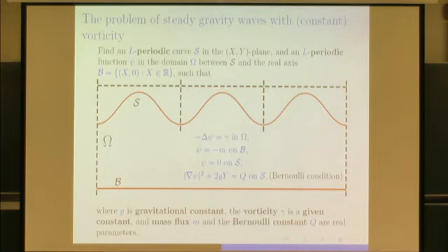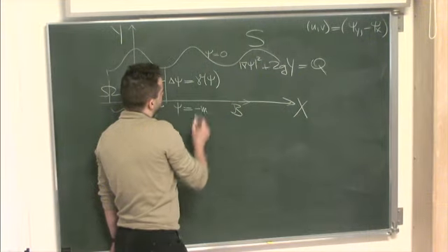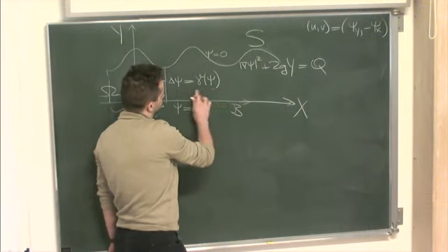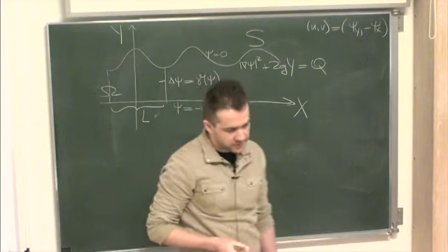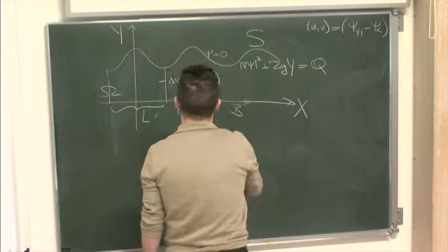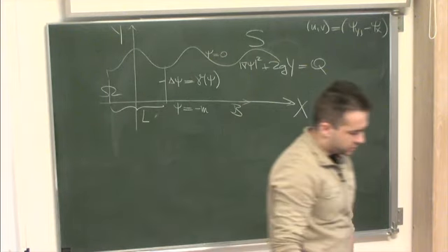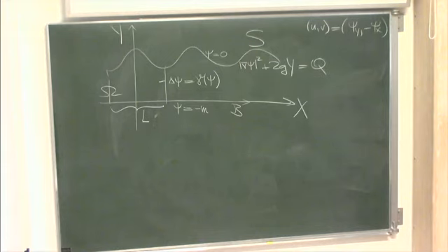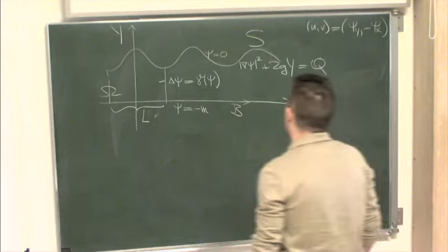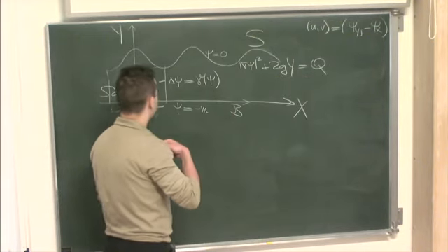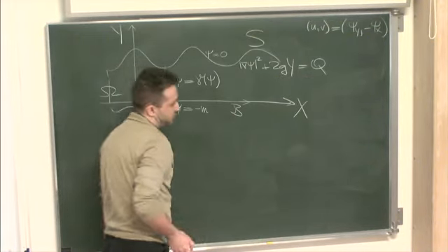So this is a particular case of the problem of waves with general vorticity, in which on the right hand side of this equation we would have possibly an arbitrary function of psi. The vorticity of this wave is minus delta psi, and from fluid dynamics considerations, it must have the same level sets as psi, and so delta psi is a function of psi.